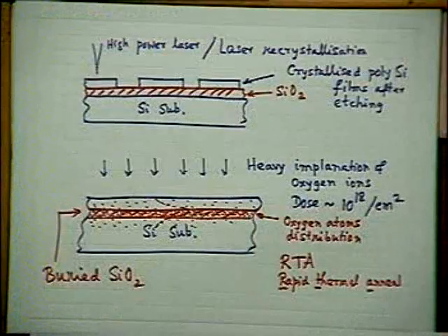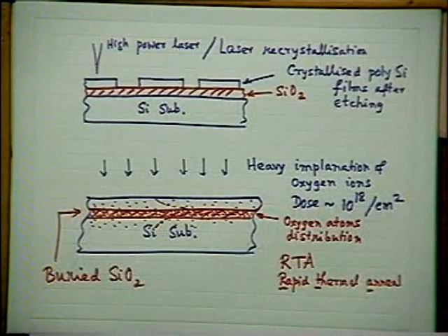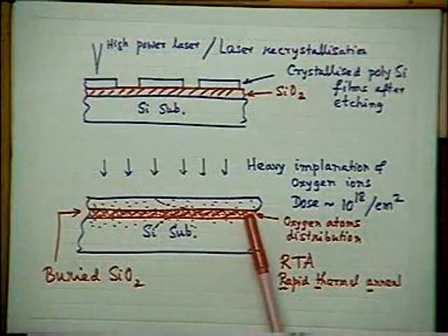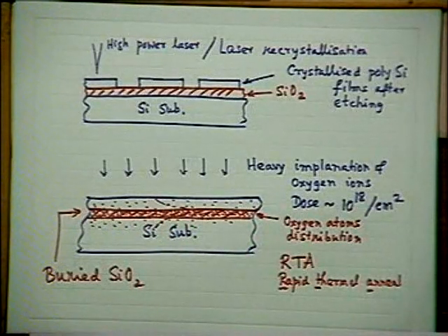Remember, in silicon, unless the impurity atoms are substitutional impurity atoms, unless they occupy vacancy sites, they do not contribute extra electrons or holes. It's called electrical activity of silicon. It depends on whether the impurity atom occupies a substitutional site or an interstitial site. After implantation, which is a non-equilibrium process, most impurity atoms normally occupy bad interstitial locations, and as a result you don't get electrical activation. Of course, these oxygen atoms are not meant for doping; they are meant only for the oxide. But still, the annealing recovers the crystal to a great extent.